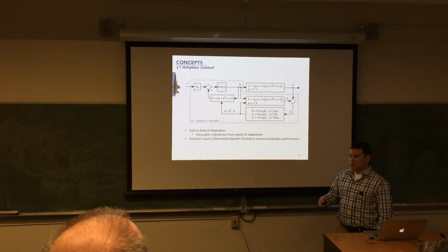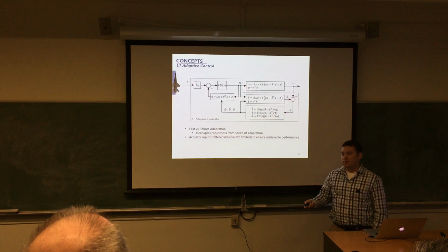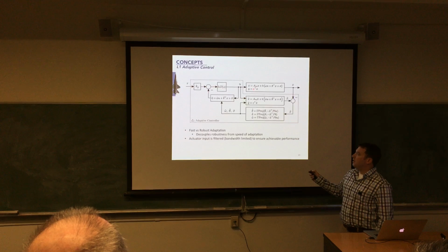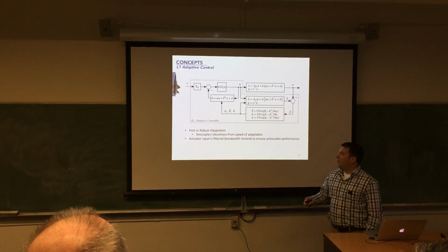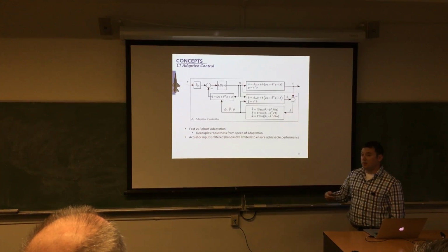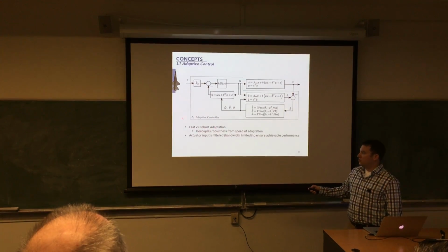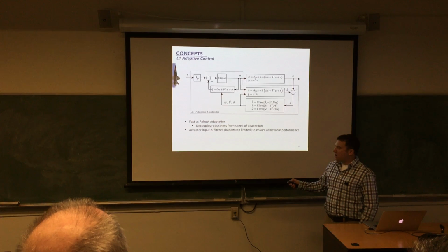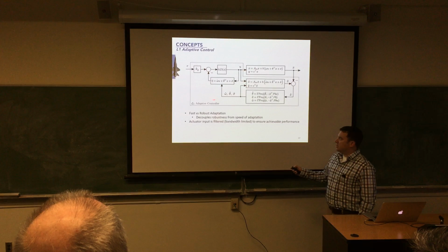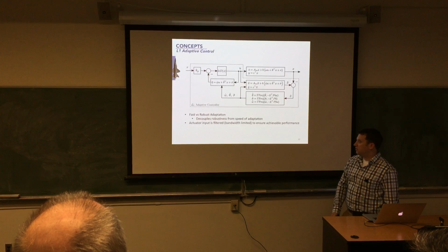So why are we trying to control the aircraft, or even model in your reference model, frequencies that are faster than you can control? If you can limit the control signal going into the plant with some bandwidth limitations, does that offer robustness? As it turns out, this specific control, the L1 adaptive controller, is ultimately why I ended up choosing it, because it offers fast and robust adaptation. With the Monte Carlo simulations, you kind of had to choose, do I want fast or do I want robust? And this specific controller decouples robustness from the speed of adaptation, which is pretty incredible.